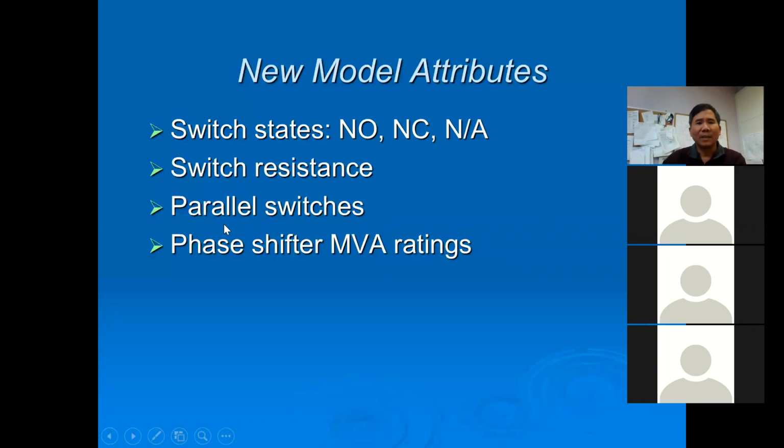You can also now enter switches in parallel if you want to, in order to represent the correct breaker configuration. Another new model parameter is the new MVA rating for phase shifter, which you can use for different PRC checking purposes.